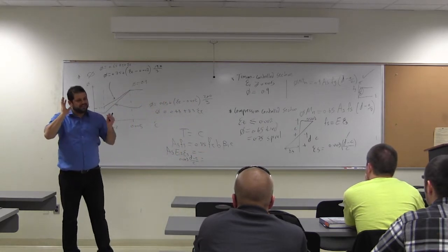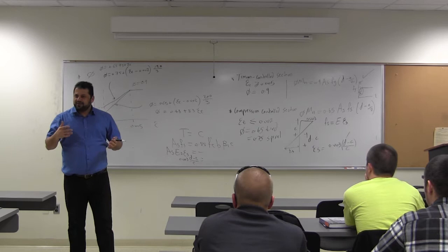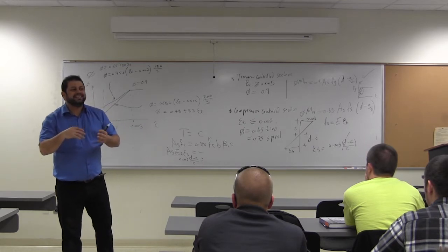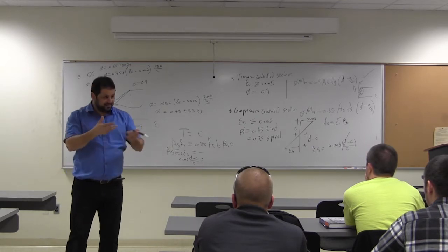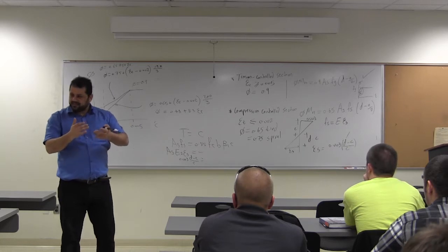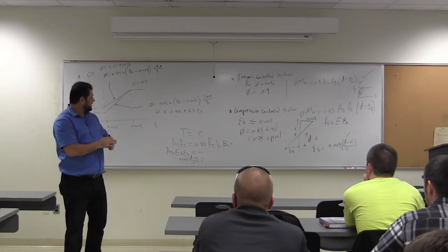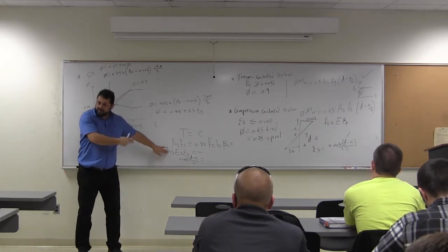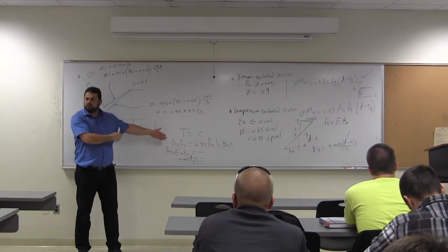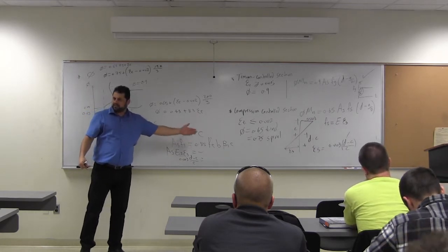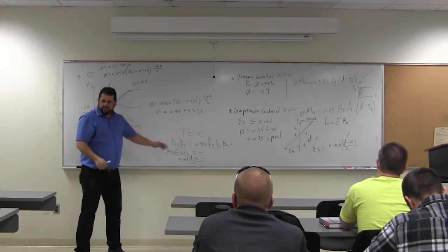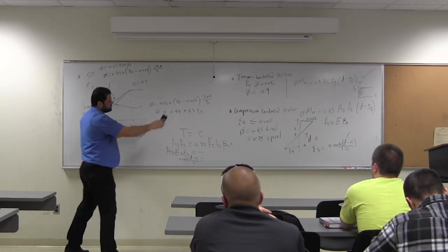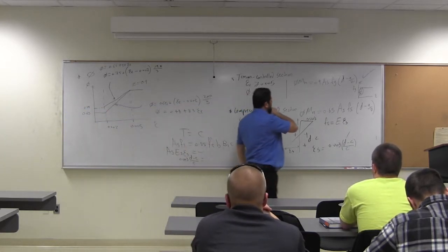You know now. So how am I going to do it? You know, guys, C is around 0.3D, 0.4D, right? 5 inch, 3 inch, so just something. That's the first step, you can guess this one and see where you are, by trial and error if you don't want to go with the solution of the quadratic equation. Okay? So that's for analysis of compression control sections.